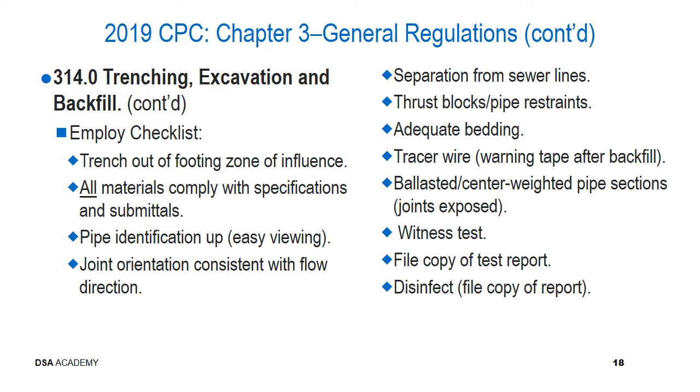And you don't want to cover the joints because you want to make sure that if during the pressure test you see a loss of pressure, you can find the leak. And the leak is going to be in the joint. That's why they have to be exposed.